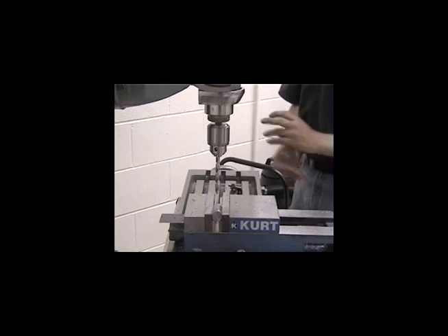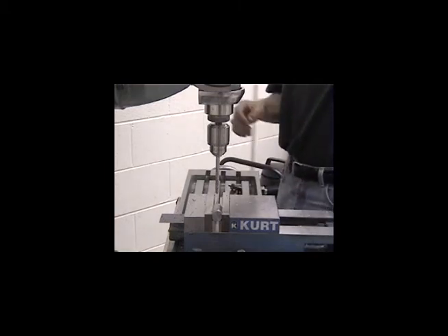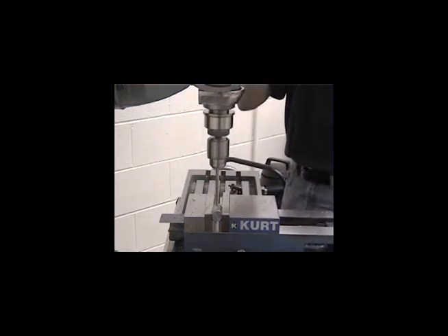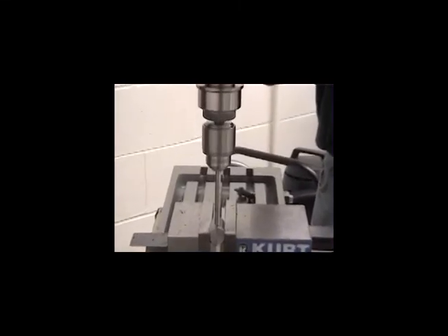It takes patience to drill a hole. Use a moderate, steady pressure. The depth of the hole is measured from the face to the end of the full diameter section. It is not measured to the deepest point in the hole.